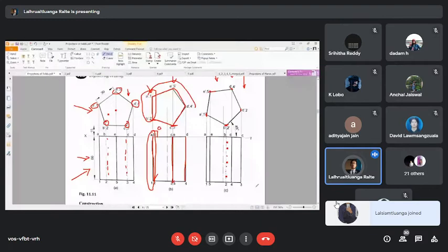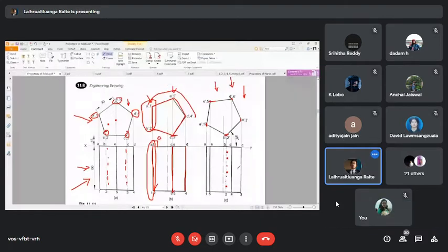Whenever we project solids, in order to draw the top view and the front view, we must be very careful about which part is hidden and which part is not. Especially when we move on to projection of solids inclined to both the reference planes, we are going to have multiple angles. You must always get those angles accurately so that you get these lines perfectly.